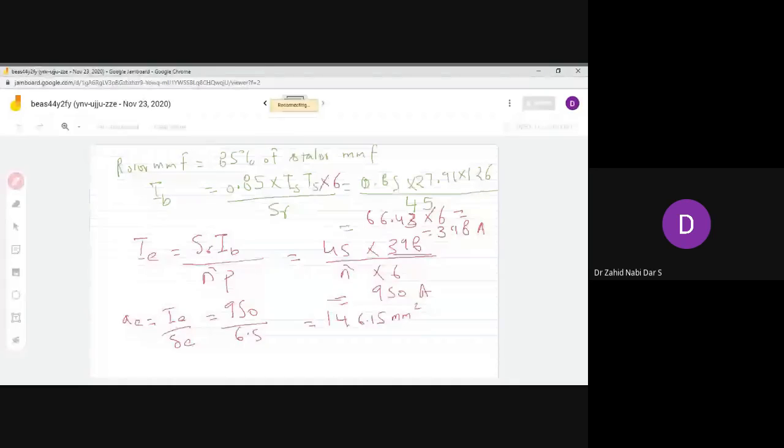Now, total copper loss in the rotor, it would depend upon what? If you take bar current into account. So in the bar current, suppose R is equal to rho L by A, but in rho L by A, you have to take all the conductors into account.